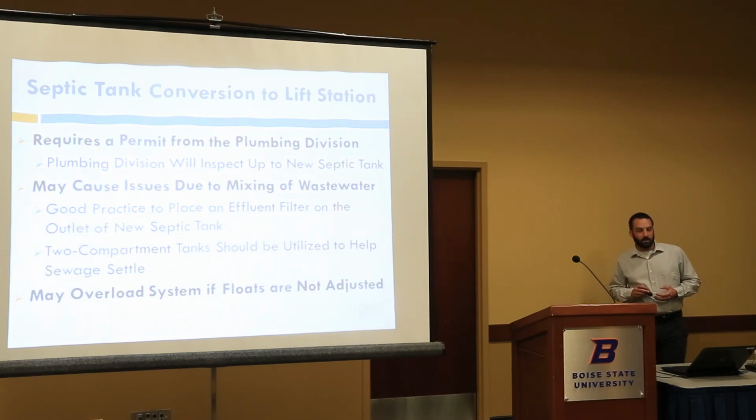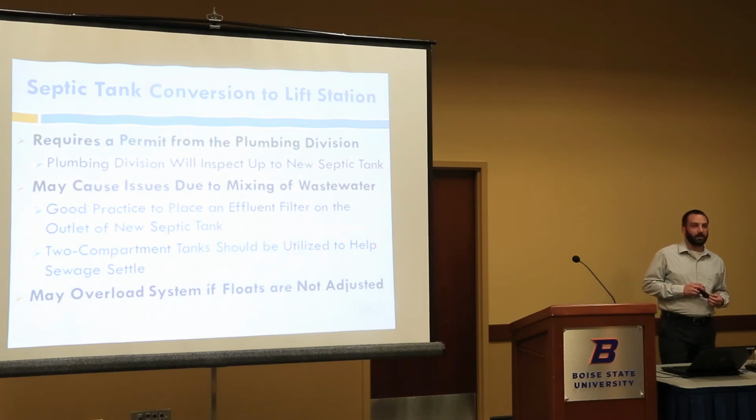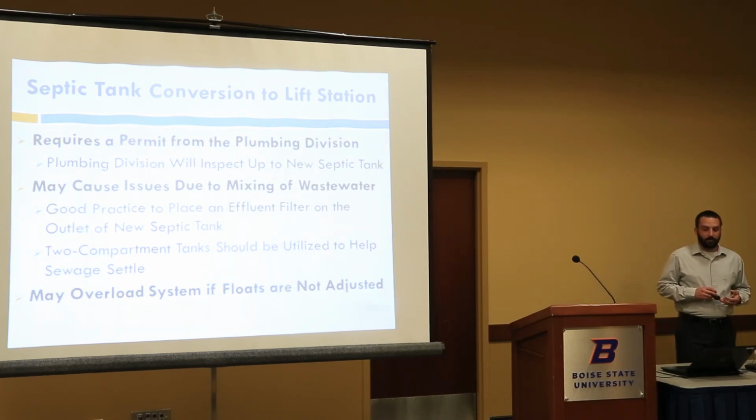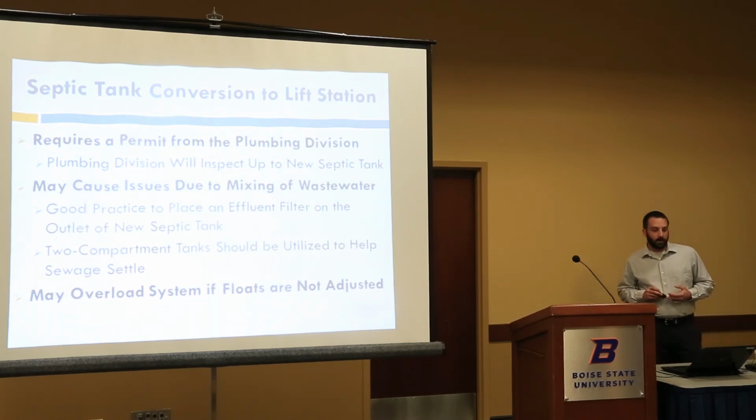So if you do this, it's a good practice to place an effluent filter on the outlet of that new septic tank. It's also recommended that you use a 2-compartment septic tank if possible to help settle that sewage out. And if you can talk your applicant into it, oversize the septic tank as well so you can get some extra retention time in that tank.